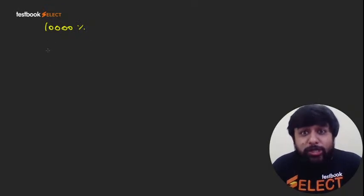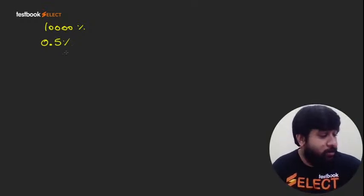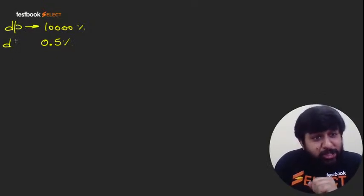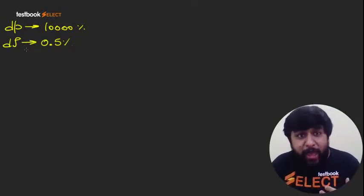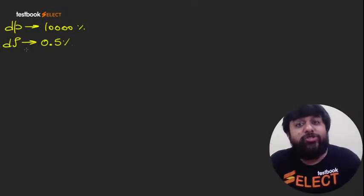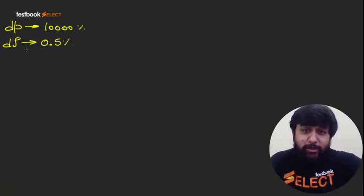When the pressure increases by 10,000%, the density changes only by 0.5%. Are you getting the point? When the change in pressure is 10,000%, the change in density is only 0.5%. That's why the change in density is so small that it can be ignored. So we can consider the change in density 0. So density is almost constant. That's why we consider that water is incompressible.